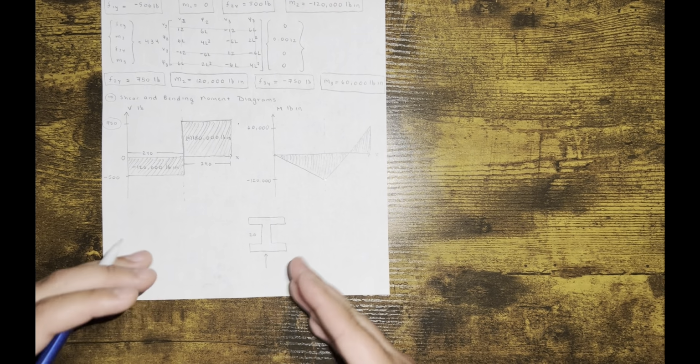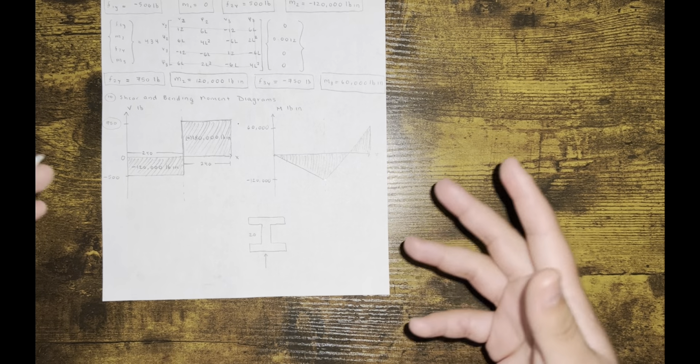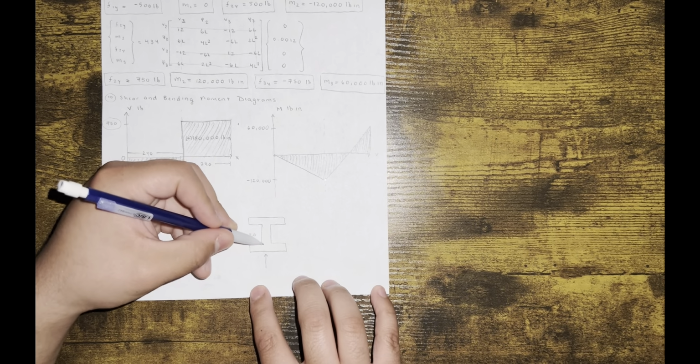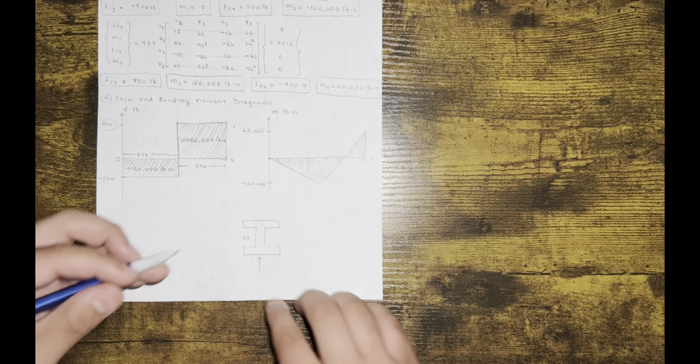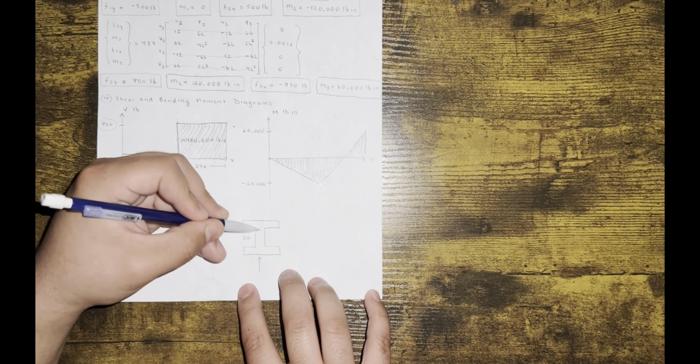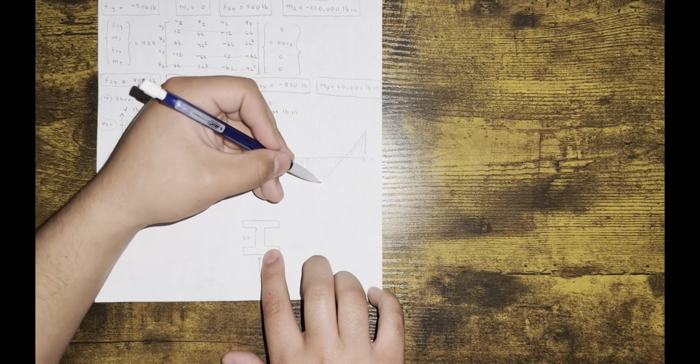37.5 pounds per inch of shear flow is happening in your beam. So you have to design that web to withstand that. And you might also have to check for buckling, things like that. And when that shear goes into your beam, it loads your caps. And that's what's fighting the moment.